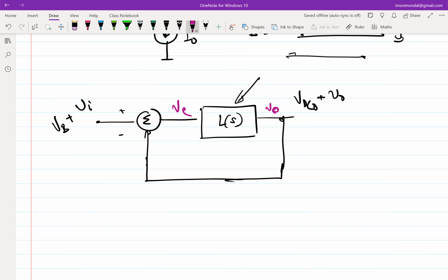That's one thing on pen and paper, and another when handling real circuits. The main issue is I want V0 over VE to be high across frequencies, because my input will not be particularly DC. My input will change, but the DC condition needs to be set by feedback also. So I can decouple these two.